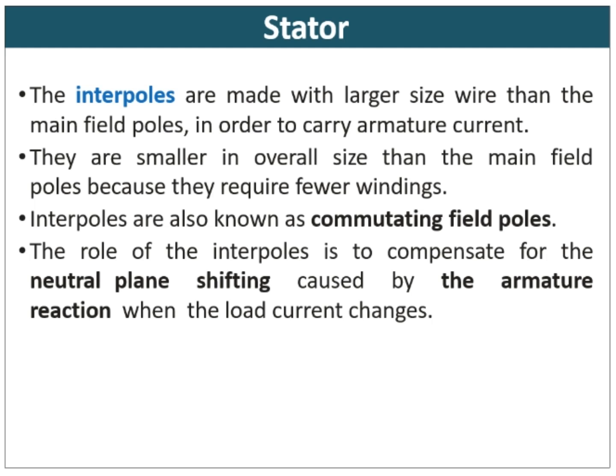Commutating field poles. The role of the interpole is to compensate for the neutral plane shifting caused by the armature reaction when the load current changes. We will explain that when we are familiar with the operation of the DC motor. And then that is about the stator.